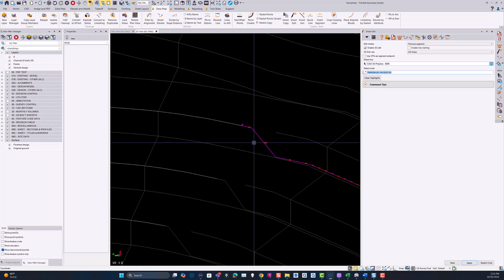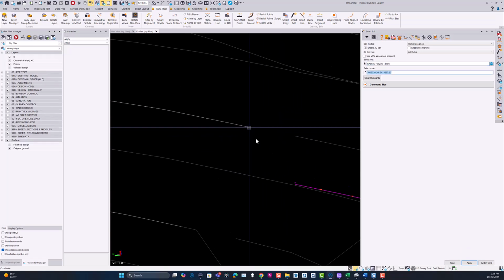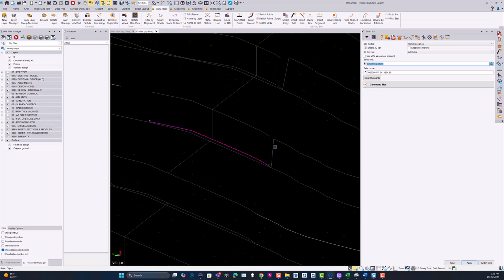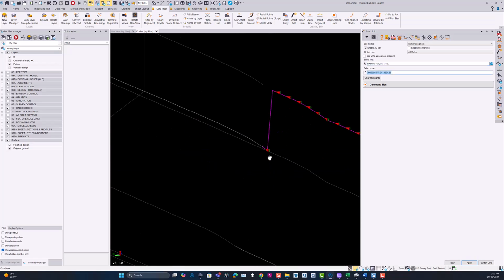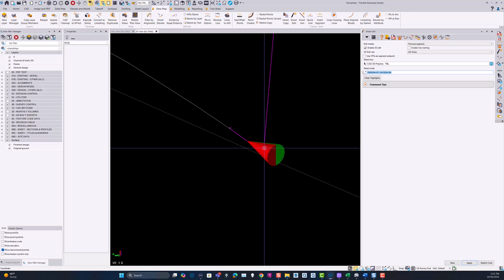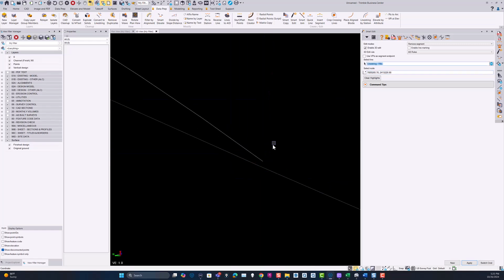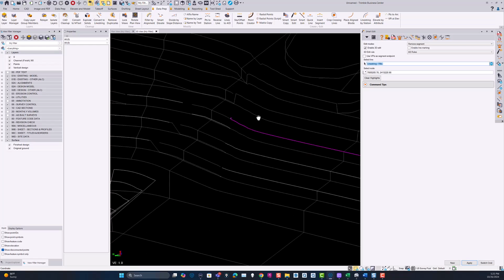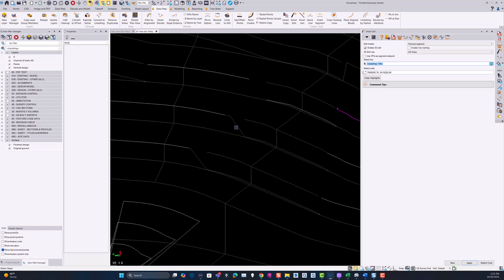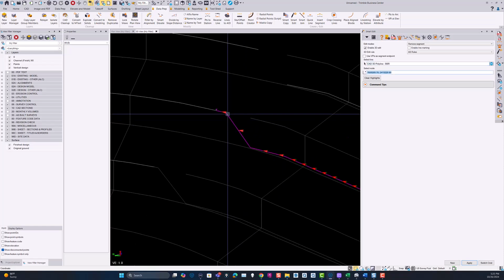So click on the line and it tells you the line direction, which is what you need to know which end of the line you're going to click. So again, very quickly in here I can run through these and click on the segment end that I want to get rid of. And work our way through that. So the line editing functions here make it pretty easy to go through this and edit out the segments that you definitely want to get rid of.